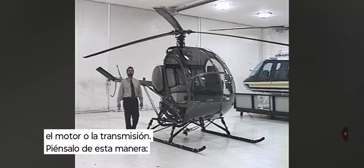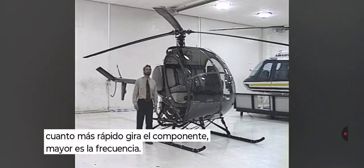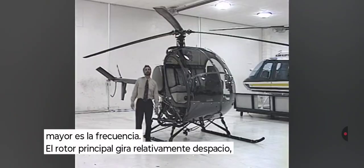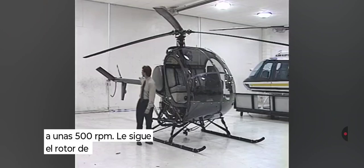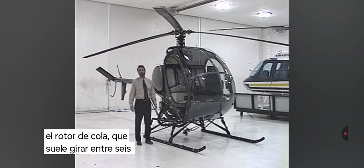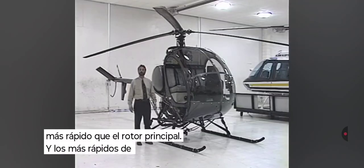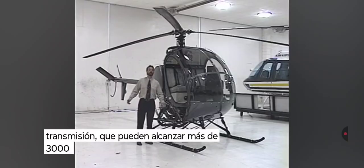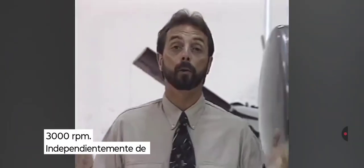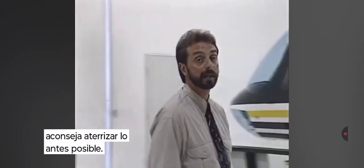Think of it this way. The faster the component turns, the higher the frequency. The main rotor turns relatively slowly, about 500 RPM. Next comes the tail rotor, which typically turns about 6 to 9 times faster than the main rotor. And fastest of all are the engine and transmission, which can run upwards of 3,000 RPM. No matter what the cause may be, prudence dictates that you get on the ground as soon as possible.